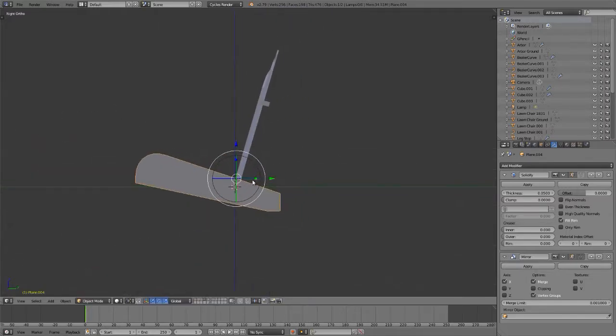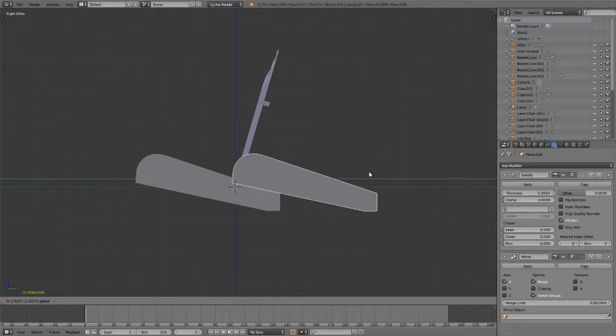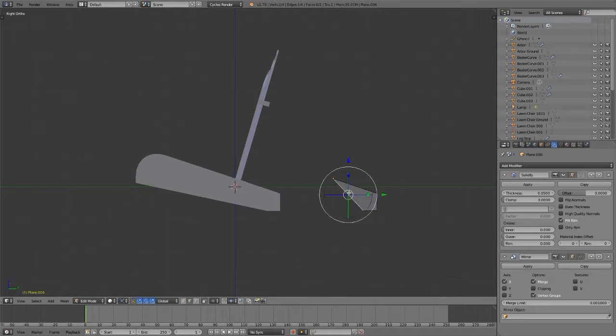Why don't we make a copy of the legs? Shift D, enter. That was a copy in edit mode. I'm going to move them back. I'm going to have a look at them. I only want rectangles. So Control, Tab, F, take anything that makes up this face and kill it. XF. Very good. Take an edge. SY0. Make it straight. This one, SZ0, make it straight. Ta-da! We now have a straight little